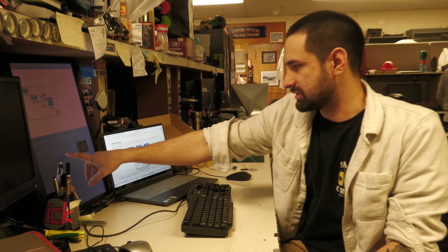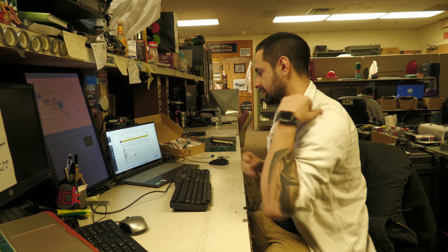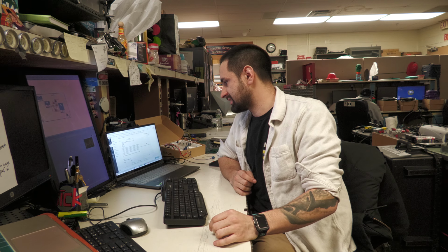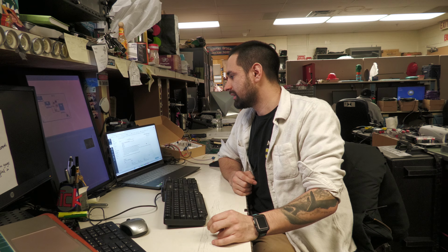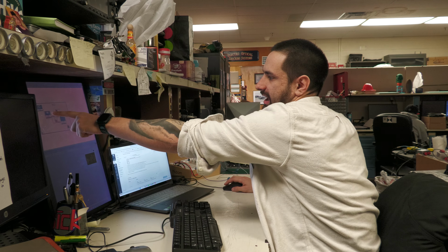On top of that, once you implement the National Instruments block diagram, you're going to want to do a few different things for the deliverables for the actual lab. One, we are going to modify the VI to save the data to a file using Write To Spreadsheet File, which I've implemented here. Other than that, we are going to clean up the input signal by adding a low-pass filter using the Filter Express VI, which I have here.